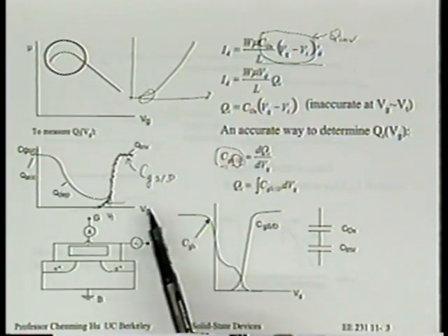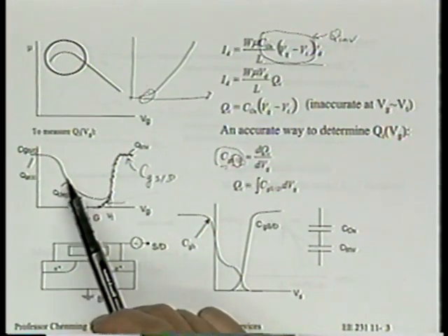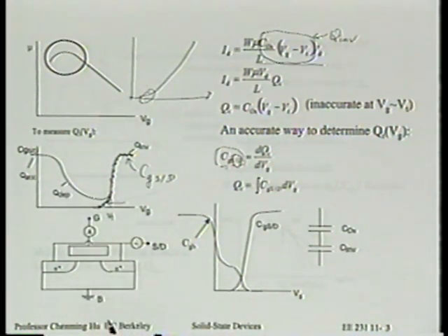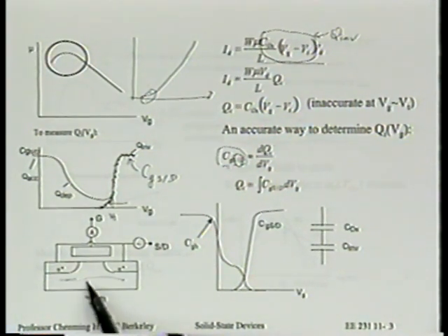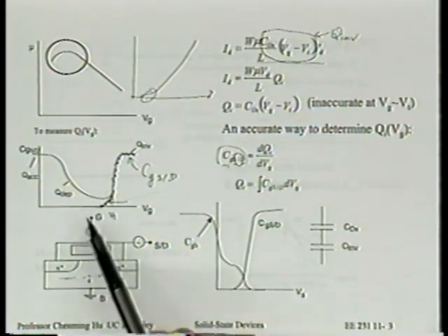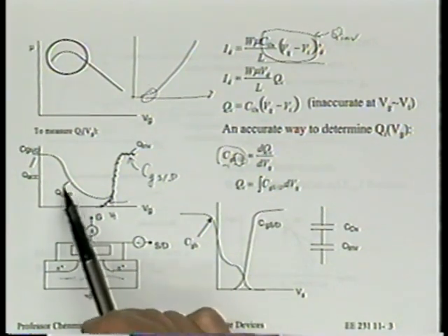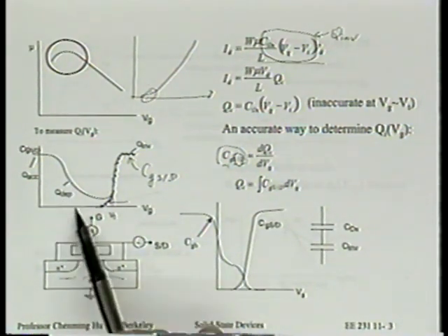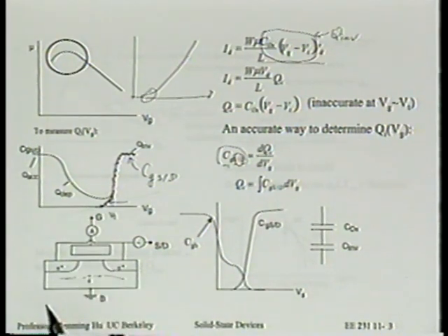All right? Now, will the depletion capacitance show up as CGSD? Let's see, in the depletion region, will the charge on this capacitor come from the source and drain? It would not. It comes from the body terminal, right? With charging, discharging, expanding, and contracting the depletion layer. And that charge comes to and from the body. Does not come from source drain. So in this portion, you will see nothing of the CGSD. That's why CGSD already will be 0 here. You follow what I'm saying?